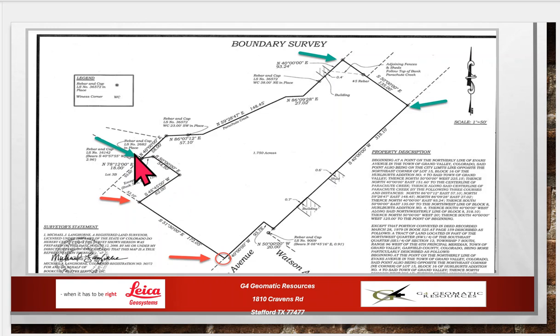The green location at this point was disturbed. We will tie this point down, this point, and this point, and use these 4 points in a one step. But as we're walking on this large tract of land in heavy brush, we can use the GPS to find these boundary corners and locate them in real time.